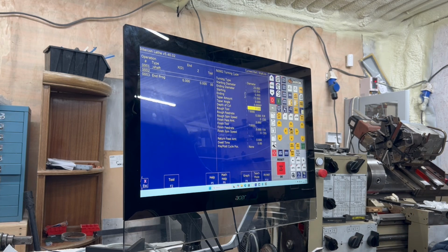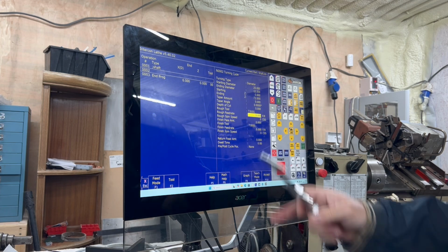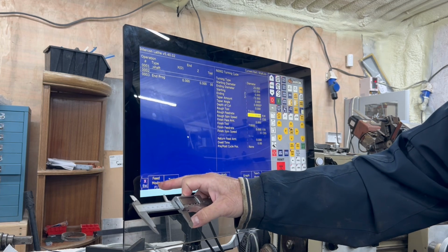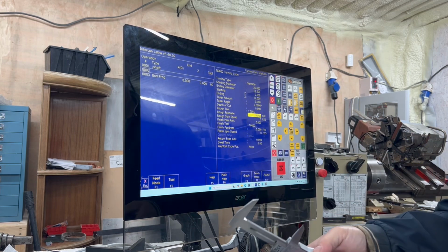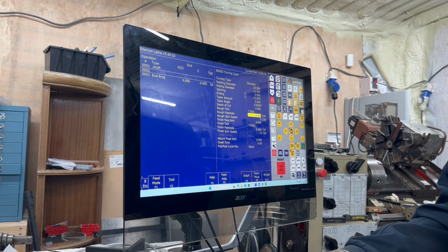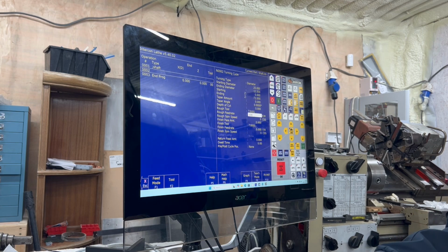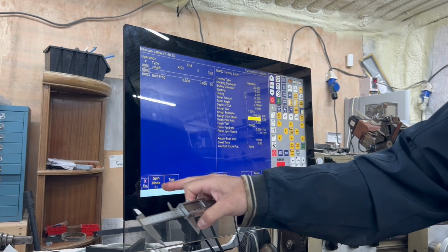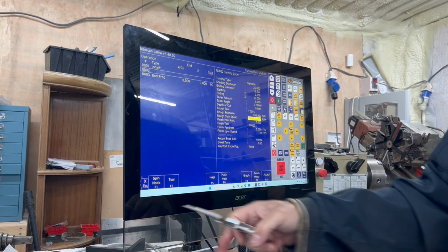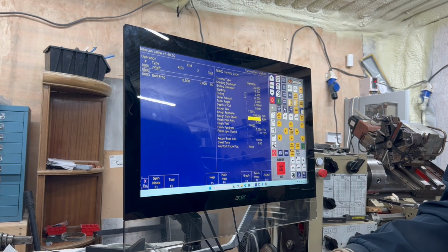Taper amount, we're not doing taper. The roughing tool I will be using is tool 1. So feed mode, so feed per minute, feed per revolution. I'm going to do feed per minute, because it's steel and I want to take it easy. I'm going to just do 100 at the start, and I can override the settings. Constant surface speed is not a bad thing, but I'm going to just put it into RPM. I'm going to put it at 1500 RPM.